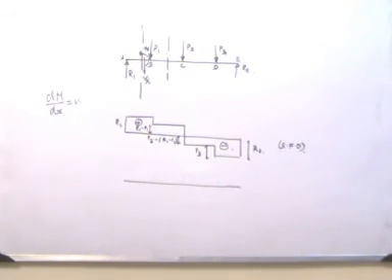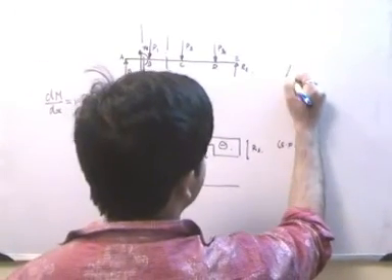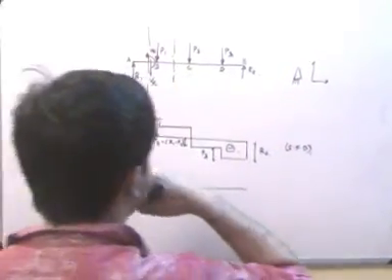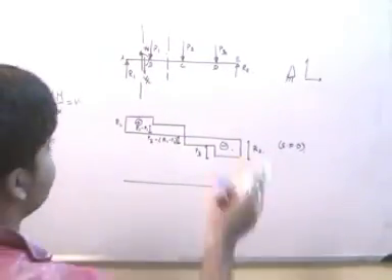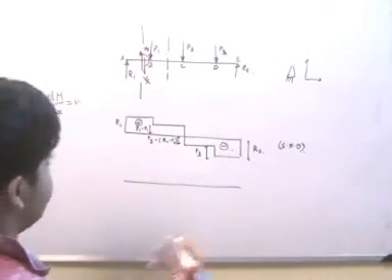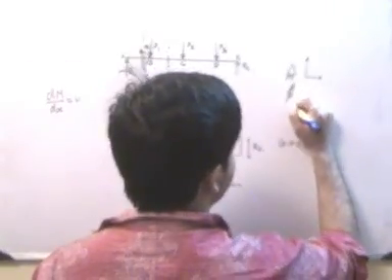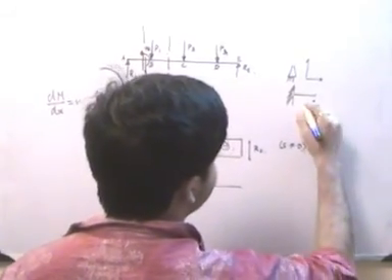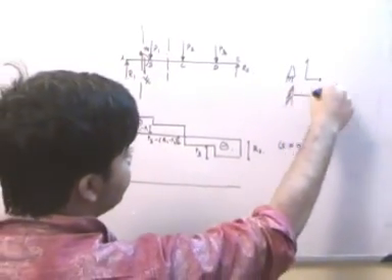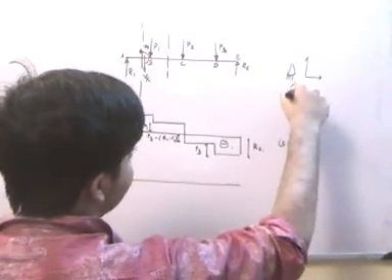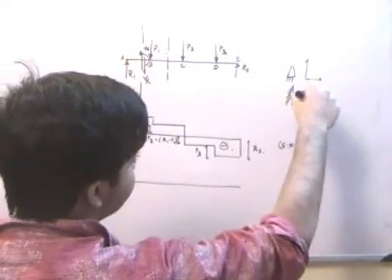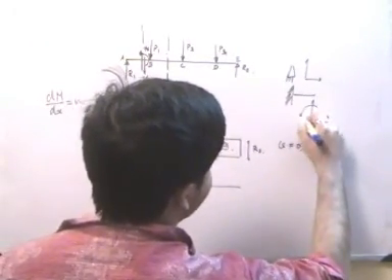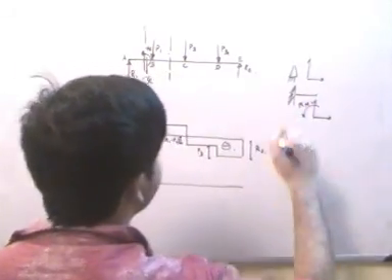Suppose this is a hinge connection. A hinge connection gives constraints in two directions, and it doesn't give any restraining moment. In a fixed connection, if the beam was like this, it gives two constraints, and there is a restraining moment: the resultant of all these forces acting creates a moment that will be taken by a restraining moment, Rm, suppose.